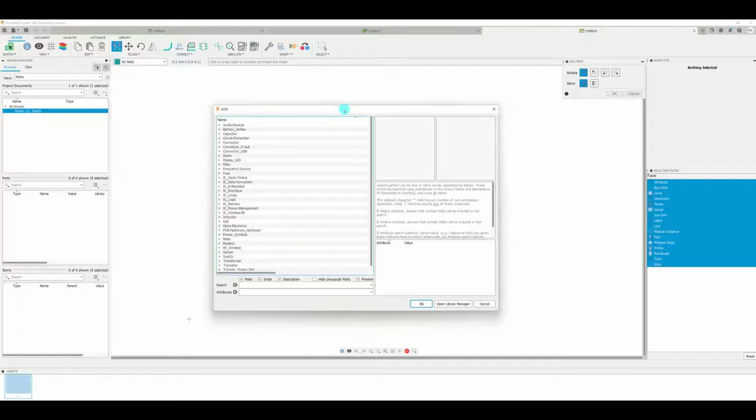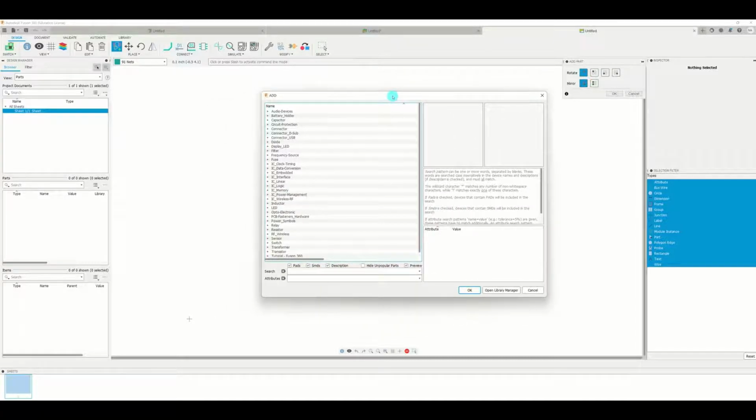So for example, in our case, we are designing a very simple circuit, making use of, let's say, a simple 244, 374, and so you can access. Okay, so let's try a very simple one wherein you have a 244, a buffer, and then you'll provide an input and an output, and then some enable. So to do that, you have to look into the component. You can actually type the search, or you can search for your logic.